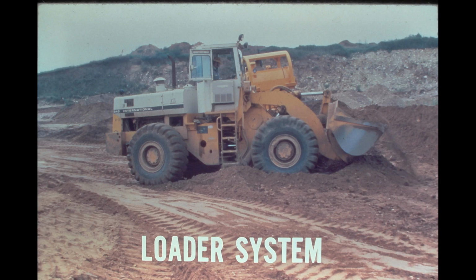The first step in troubleshooting the loader system is to take time to study what the problem is. The possible faulty components can be narrowed down just by watching how the machine functions. If the loader is slow at high engine speeds and the steering is fast, the diverter valve in the steering switch pump could be stuck in the low speed position. If it is stuck in the high RPM range, the steering would be slow at low RPM and the loader would be fast. If the loader is slow at high RPMs and the steering is slow at low RPMs, then the probable cause is the switch pump.